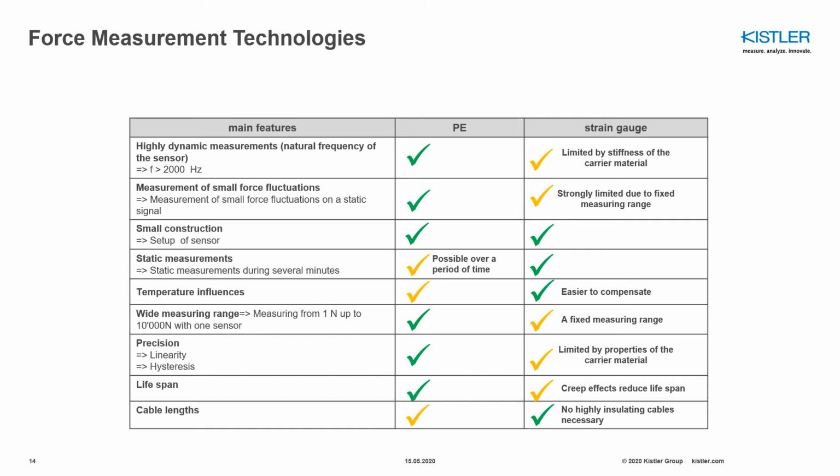The piezoelectric technology enables highly dynamic measurements due to the high natural frequency of the sensors. It enables measurement of small force fluctuations, gives a wide measuring range, and has high precision due to the linearity and hysteresis characteristics. And the product life is often much longer than strain gauges.